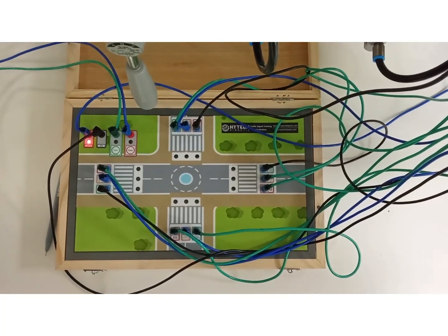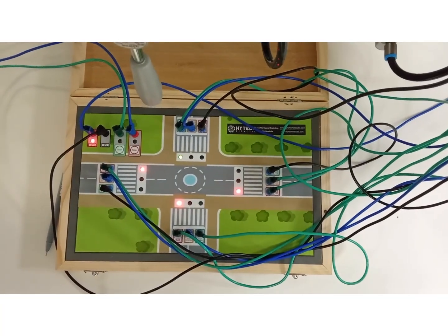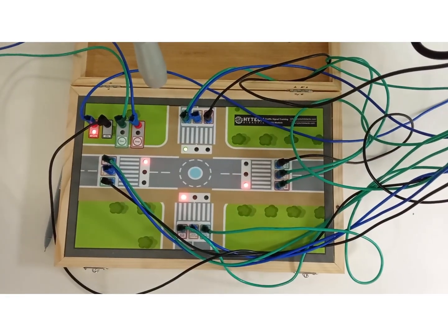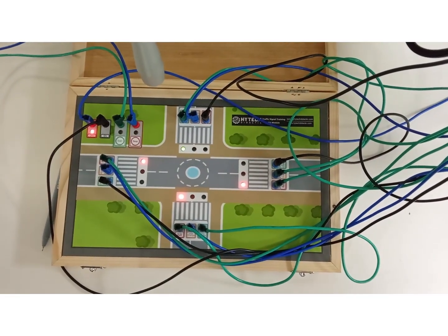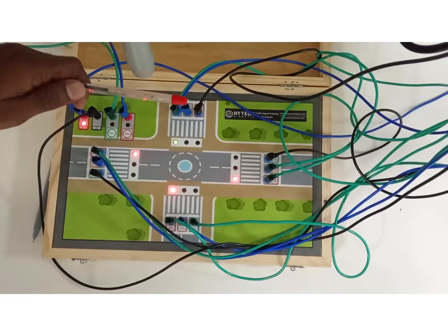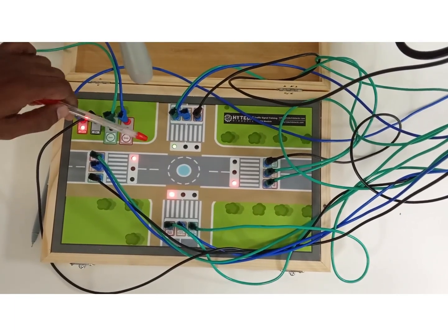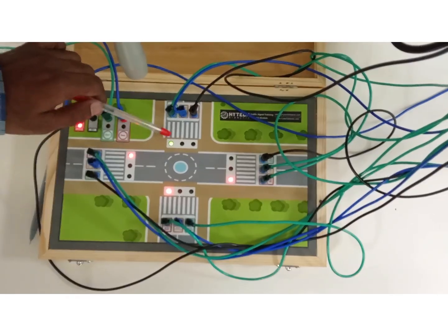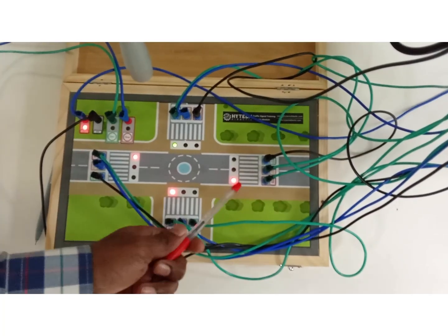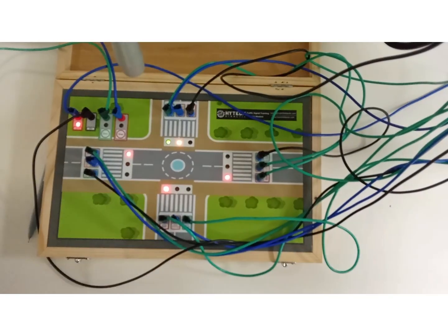Once we start using the start button, by using the push button, or this switch, or the X0 switch, the route 1 green color is on for 25 seconds and the timer is simultaneously on and counting. While the timer value is between 0 and 25, green is on, and the other 3 are in red.